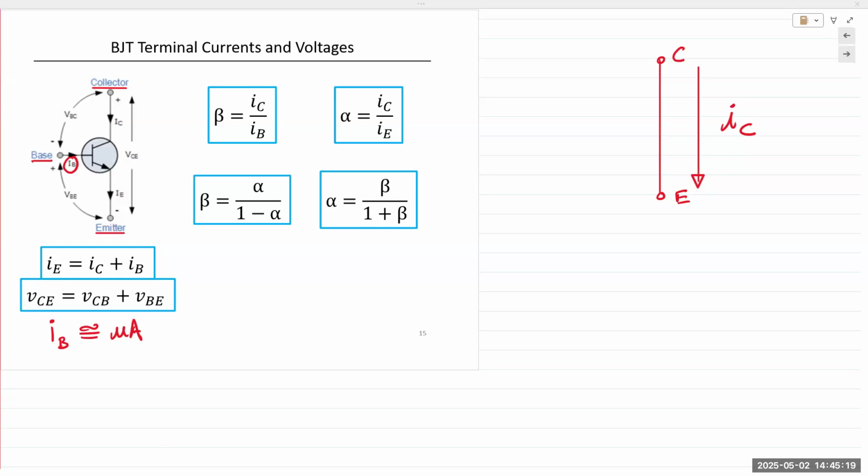So we are isolating the input from the output. Any current that the follow-on circuit needs is going to come from that unity gain amplifier and not from your input. And that's the point of application of the unity gain amplifier. It's actually a very important configuration in electronics. We can use op amps to create an isolation or unity gain amplifier.